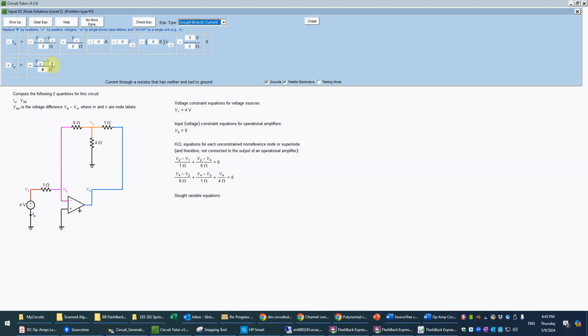So the current going to the right through the 1 ohm will just be the voltage difference driving that, which is V1 minus V2 divided by that 1 ohm. And that'll have to be the same as the current going up through here. So again, the voltage source does not control its own current. It's determined by something else in the circuit, which we're illustrating explicitly here.